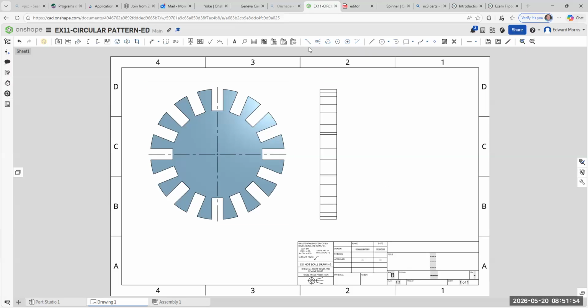Now look, we're going to come here. You see this one? This is a 2-point center line right here. Click on that. Now look, it will snap to the center. Click, and then come here and snap to the midpoint of that arc. Boom. Hit escape. You're going to do that again. Go to that center line, click on that center, and then come out here. Go to the midpoint. Click, hit escape. All right, do you have those?